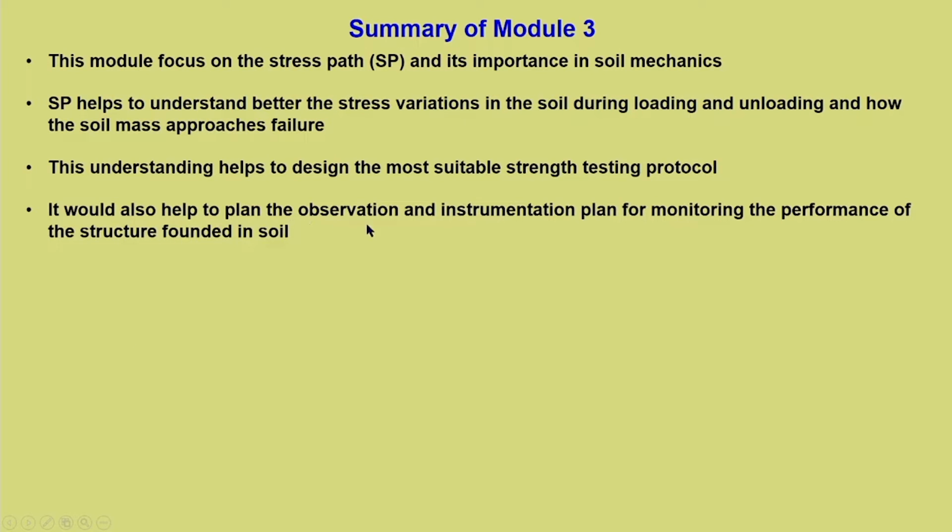It would also help to plan the observation and instrumentation plan for monitoring the performance of the structure founded in soil. So, let us say that we are interested in doing some sort of monitoring. The stress path analysis in the beginning helps us to focus on what exactly and how and at what time we need to monitor. So, the instrumentation plan or sensor placement and its operation can be planned with the help of initial stress path analysis.